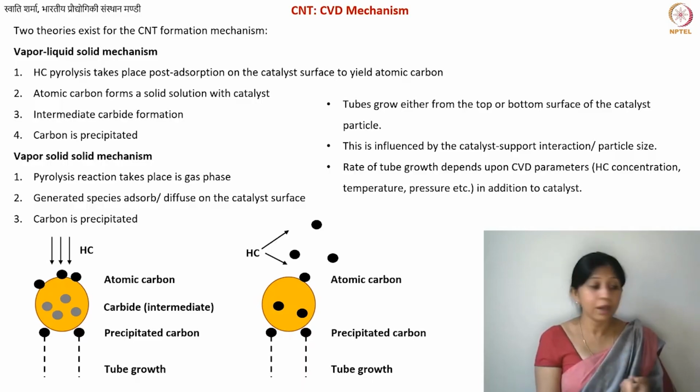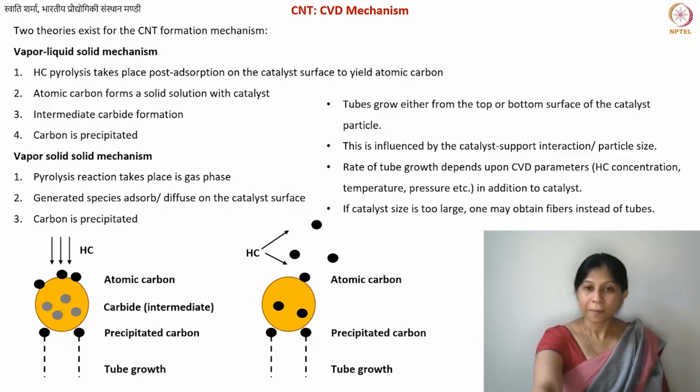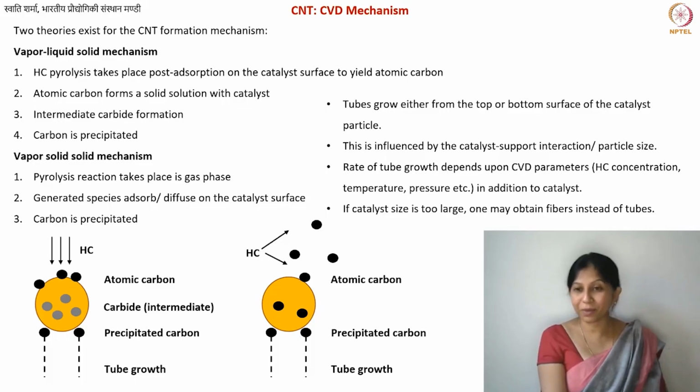That is also important. You also have some other parameters such as the concentration of your feed gas and the residence time of your feed gas, typically between 15 to 60 minutes. Again, all of this has been reported. So based on all of these parameters, you can optimize the growth of your carbon nanotubes and the rate of the growth of the carbon nanotubes. Also, the carrier gas can become important, and so all of these factors, similar to any other CVD reaction, you can perform the optimization.